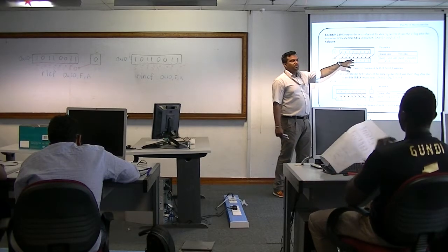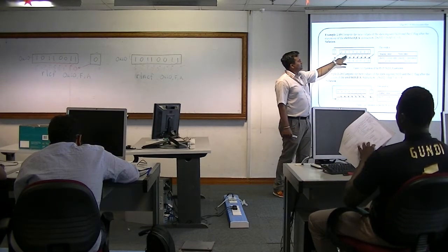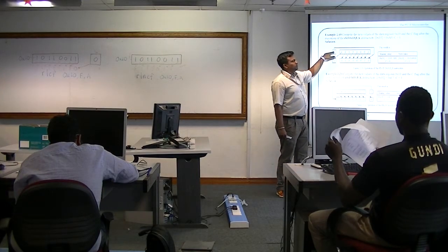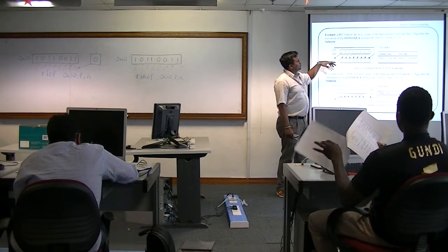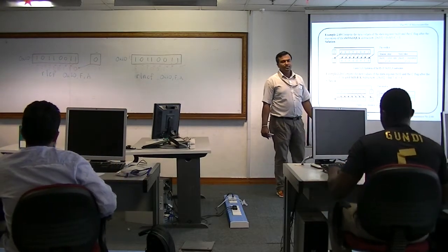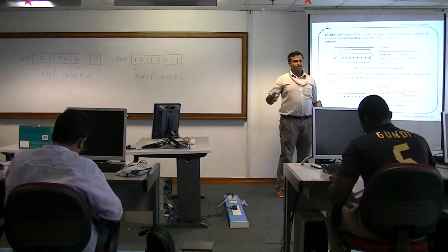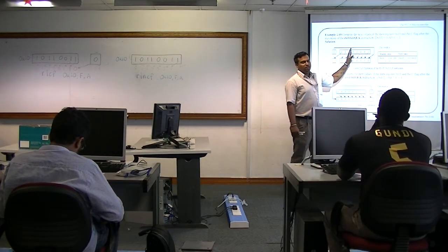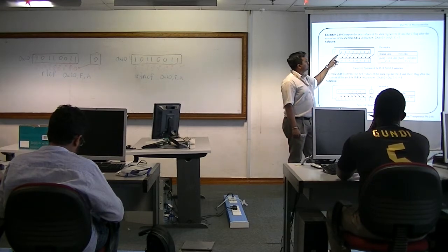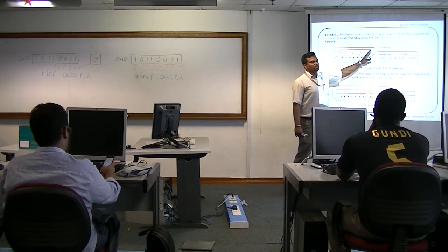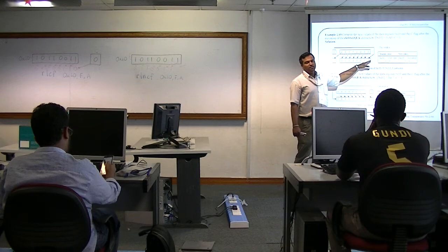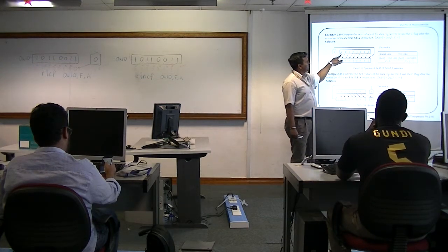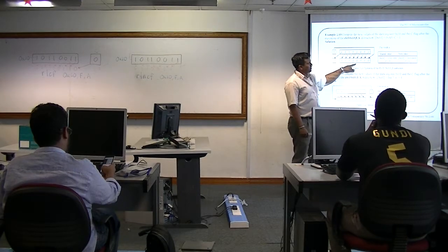By drawing the register, and you say A9 means this is A, this is 9, and the initial C should be 1, right? So when you rotate left, it means right to left. From the carry bit it should come like this. You push from right to left. If this is through carry, the carry bit should come to the least significant bit first. So you push, and the last one should enter. So this value is actually wrong.